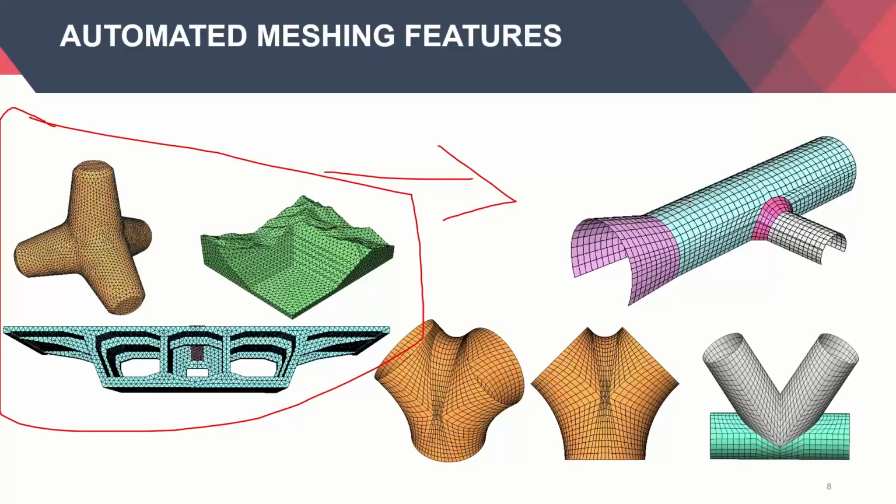That is why the computation time is a bit lesser for the hybrid elements, and also the results are a bit more clearer. Again, the results between the hybrid mesh and the tetra mesh would not make much of a difference for the exact same type of mesh size and analysis. What will differ is the total number of nodes in each of the element choice types you have.